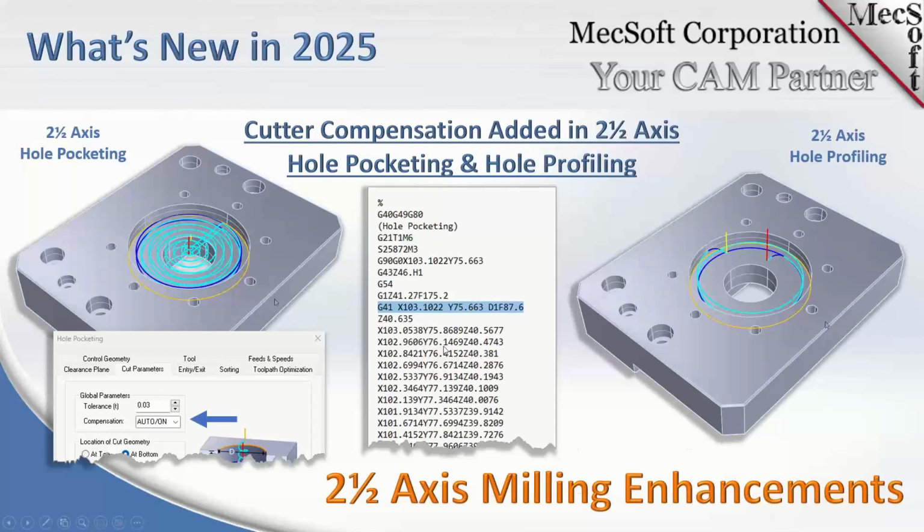We've added cutter comp for hole pocketing. On the left, you see hole pocketing. On the right, you see hole profiling. Over here in the dialog, it works exactly the same way as other cutter comp in other 2-axis operations. Just turn it on.